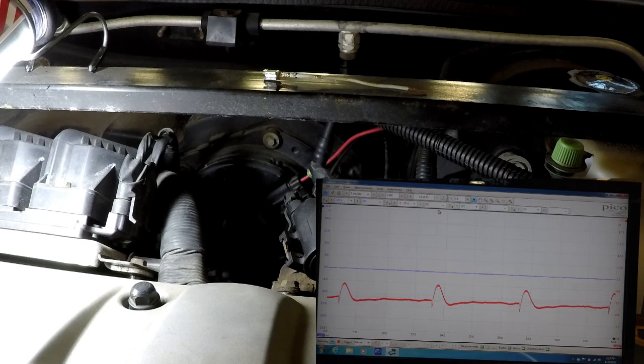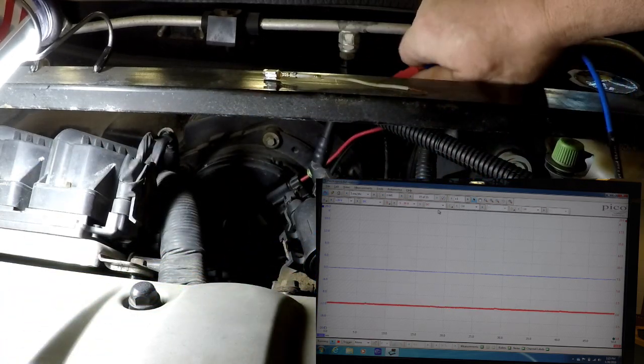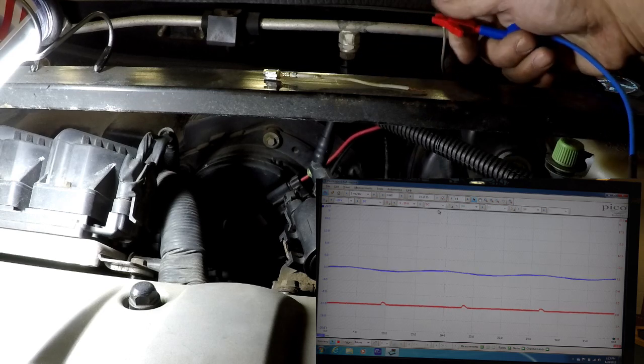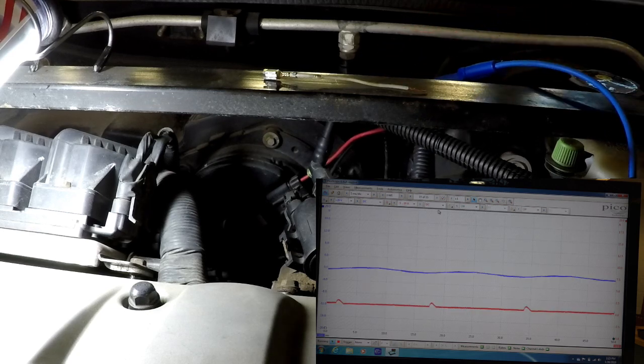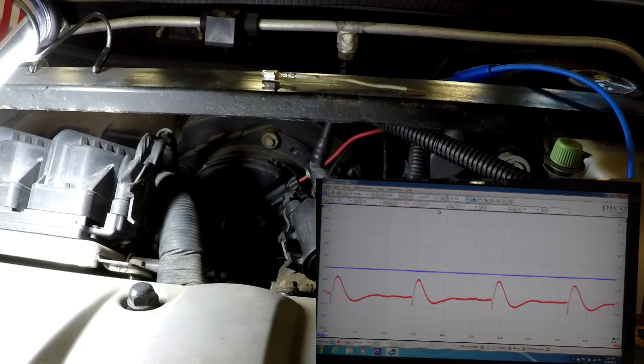We'll see if we've got anything going on there. All right, it is connected to the wire coming from the programmer, and we've got a nice straight zero line, so that programmer's not doing anything. All of the voltage, all of the current that we're seeing is coming from this blower motor itself, or the controller that's an integral part of it.